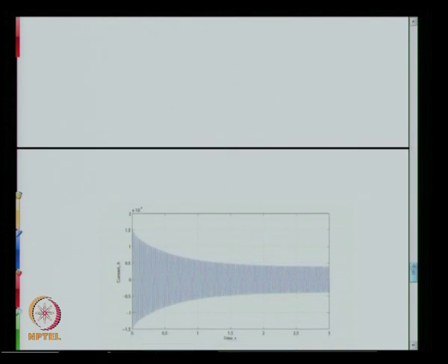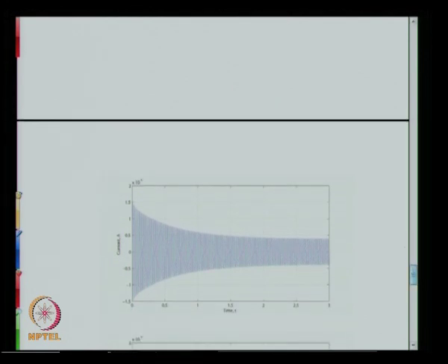So here we have the flow of current Ia of t calculated from the expressions that we have derived. We see here that there is a steady state part. So after all the exponents have decayed down to 0, what results is then called the final steady state short circuit current.